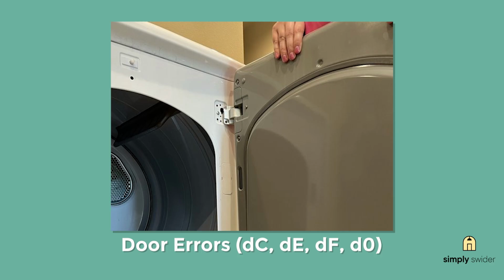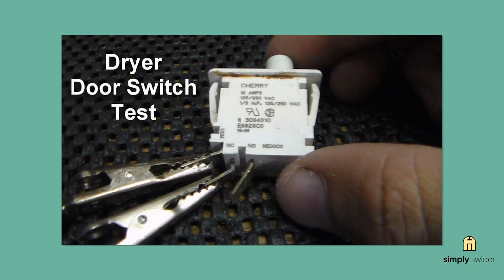Door errors are super common and usually pretty easy to fix. You'll see DC, DEDF, or D0 on the display when something's wrong with the door latch or sensors. The dryer either won't start at all or it'll run with the door open, which obviously isn't safe. Most of the time, you've just got something caught in the door, a sock, part of a shirt, whatever.